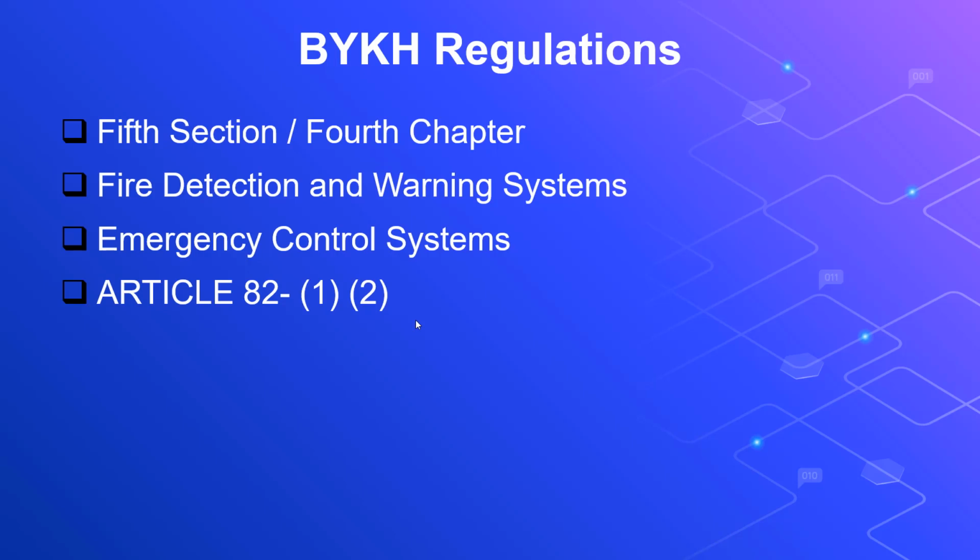Restricting the use of elevators during a fire based on their construction features or ensuring their use by fire brigade or trained building firefighting teams for evacuation processes. Automatically notifying the local fire department, the electric utility, the municipality, the police or gendarmerie, the institution's supervisor, the building owner, and other necessary places in the event of fire.